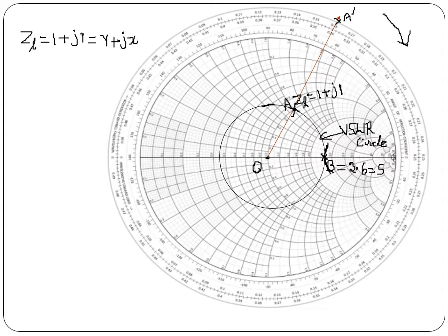We can see in your Smith chart, the outer circle shows reading in wavelengths toward the generator, and the arrow is like this. The next circle shows reading in wavelengths towards the load, and the arrow is like this.